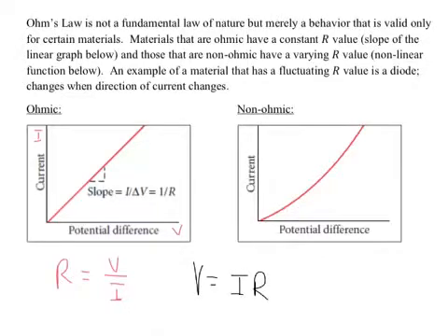And the reason we can tell that, remember, here was our original formula, V equals IR. In this graph at least, R is thought of as almost like your slope. If R is constant, the slope should be constant. This is like your dependent, and this is your independent. The graphs here, these examples, happen to switch those two. They plot current versus potential difference.